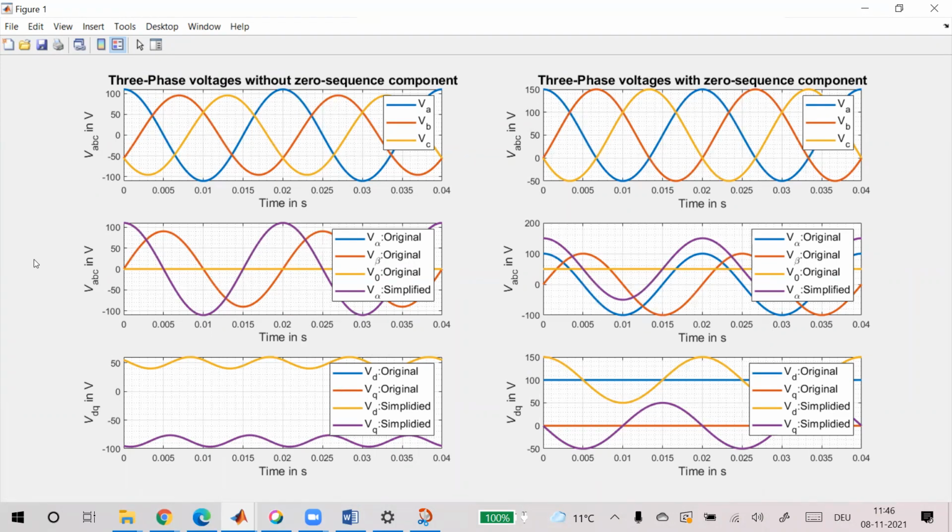And you see the D component and Q component offsets are not equal to 0. So the offset value is not 0. So for sure, what has happened is the phase has not aligned. The park transformation angle is not the same as the positive sequence angle.